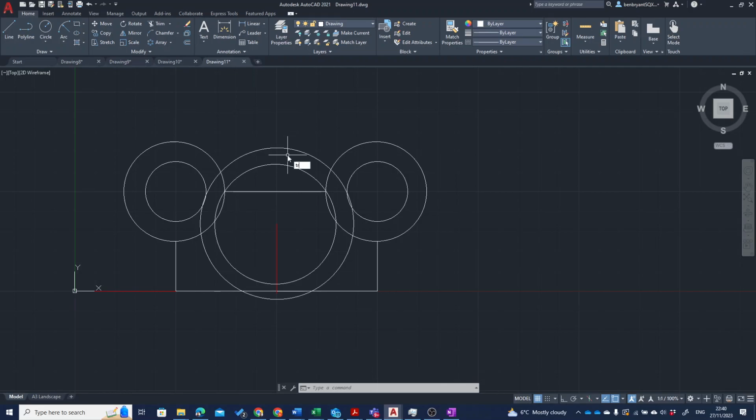So now I'm going to go into trim. Now a top tip here is as soon as you trim both sides, you get there and there. And this side over here. People then start to go around and then trim all the rest of it. If you trimmed, you made a cut, click on the rest of the shape you don't need, delete, click on that shape that you don't need, also delete. You don't have to worry about trimming everything out, like so.